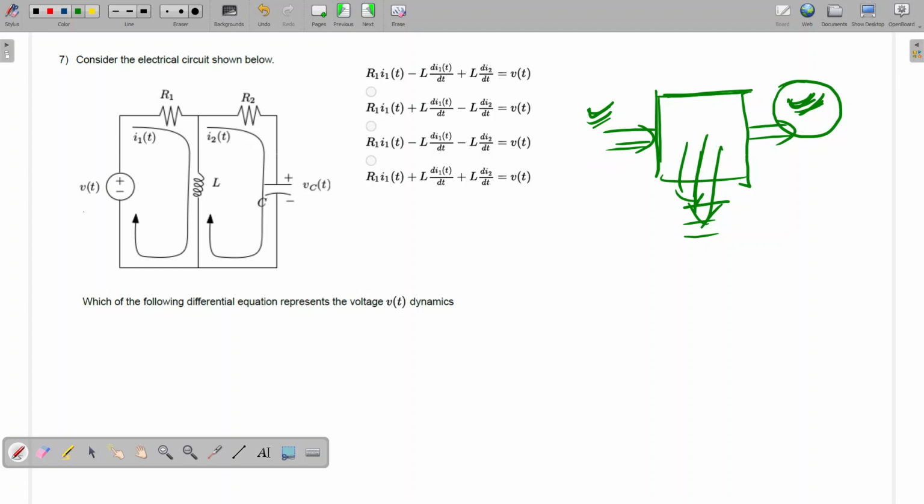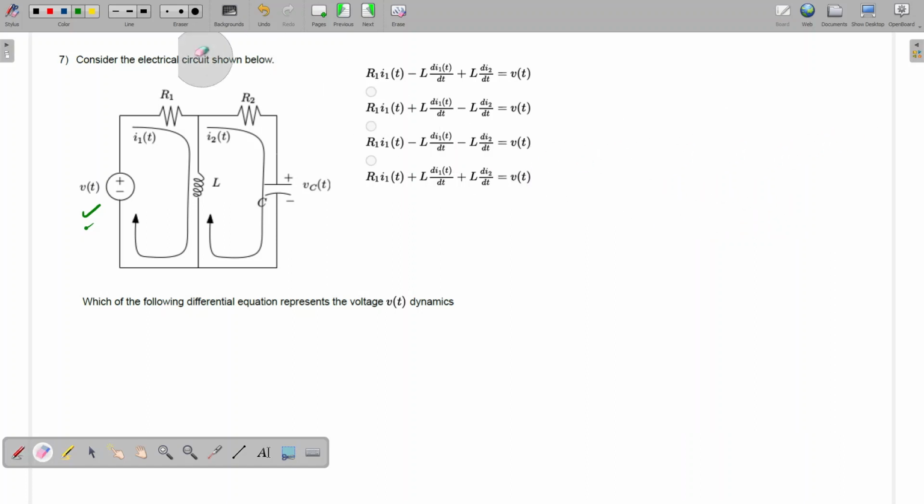Similarly, in a network, we apply some voltage and at a particular point we get some current or some voltage. That voltage divided by this voltage gives some transfer function. Let's say an electric vehicle model or a power converter: every system will have some plant transfer function. That transfer function we should know first. If we know it, then we can design a controller for that kind of system to make it stable.